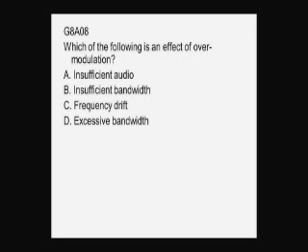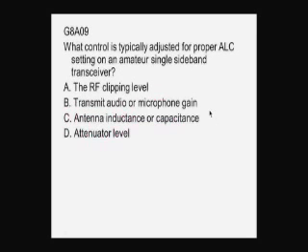Would we have frequency drift? Probably not. Modulation shouldn't affect frequency. But we would have excessive bandwidth as a result of overmodulation.